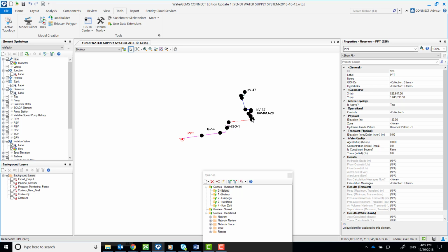Use customer meter data if you have it, also to help you match the demands, because getting the demands right is what's going to make an important difference for your models. Once you have certainty on your demands, you can start calibrating for other things like roughness. But it sounds from the paper you sent to me that most of your difficulties might be the leakage that you have in your system.